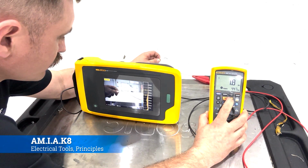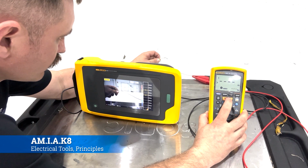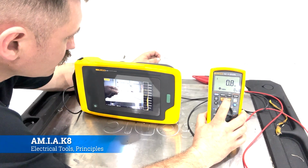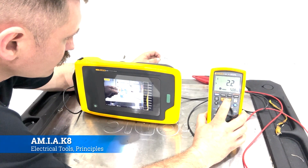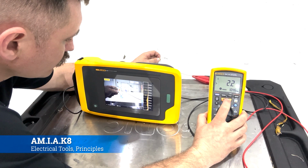Here's a little bit more creative way. We've got the megger that we're doing an installation test with, so it's sending voltage down a wire that's been shorted. We're combining that with an ultrasonic imager, and as the wire arcs, it's starting to make noise. As it makes noise, the ultrasonic imager picks that up, and it highlights the area visually where the short's at. So you can imagine how useful this would be in trying to find a short somewhere in a large airplane.